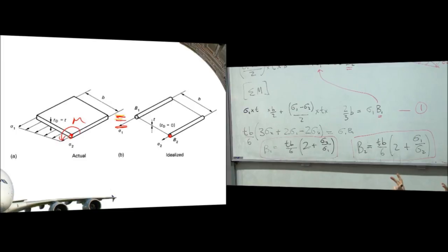If we just apply a net tension to a structure, the direct stress should be constant everywhere. The thing that causes variation of direct stresses is bending, because you've got compression at the top for a normal wing, tension at the bottom, and you've got a variation in stresses as you move around. So if we think about a bending calculation,